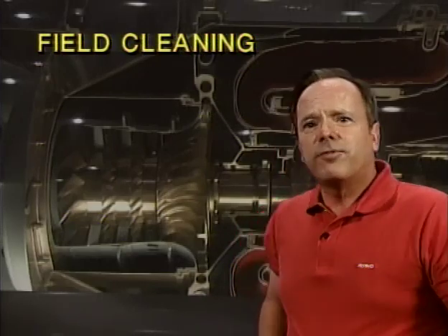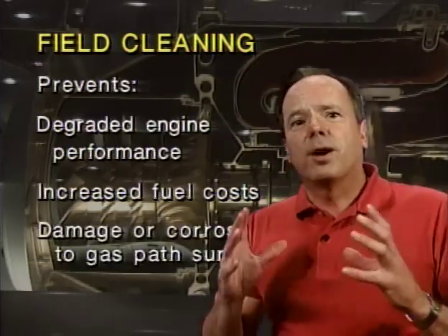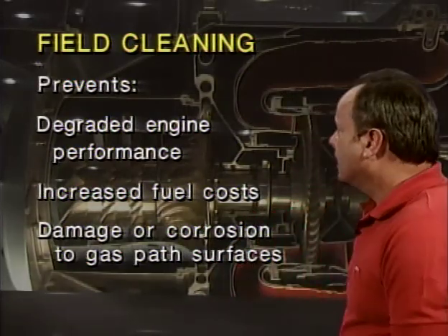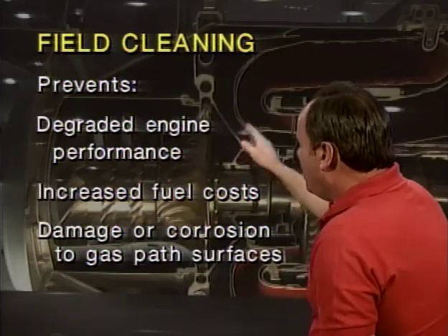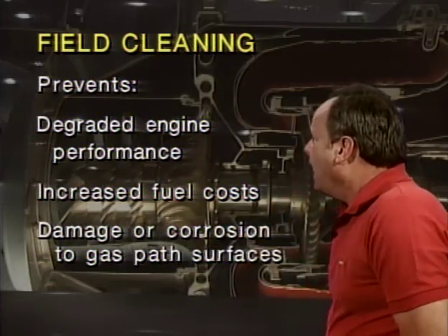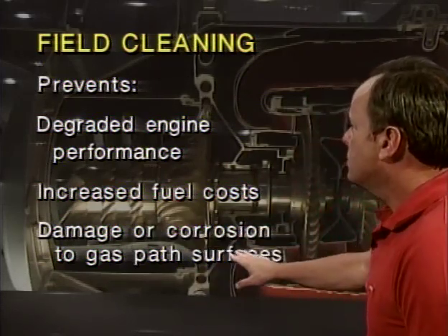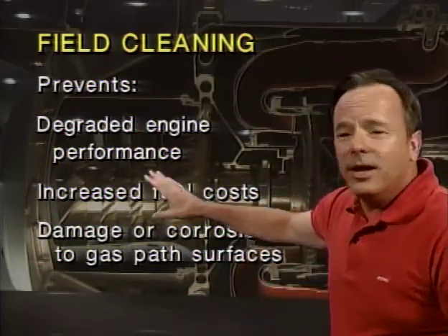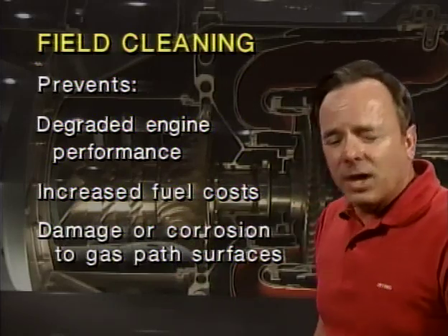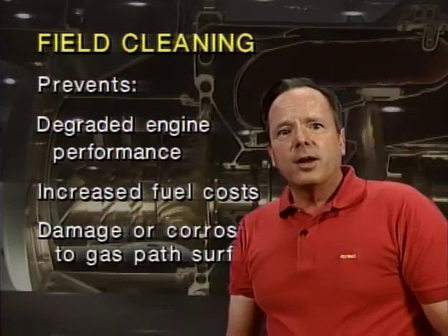Now, compressor field cleaning on turbine engines is performed primarily to do these things. It will prevent degraded engine performance, it will prevent increased fuel costs, and it will prevent damage or corrosion to gas path surfaces. So they want you to have the general idea that taking care of those compressor blades and keeping them clean is a very, very important thing.